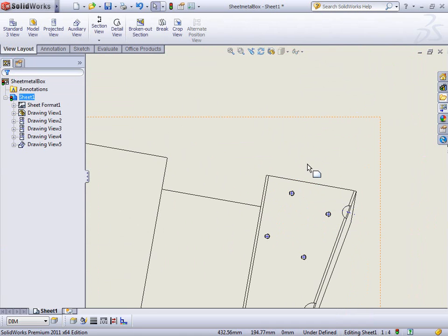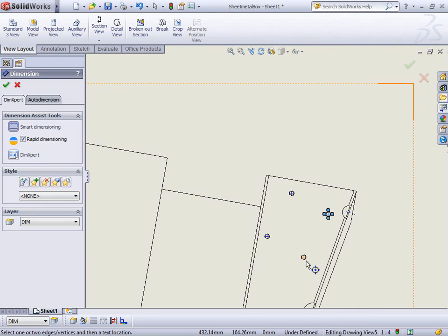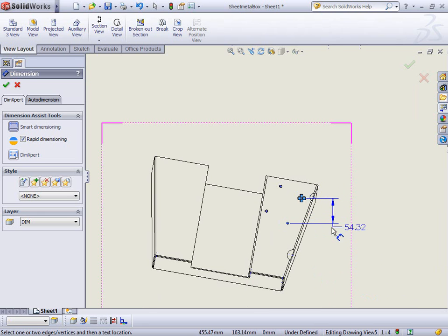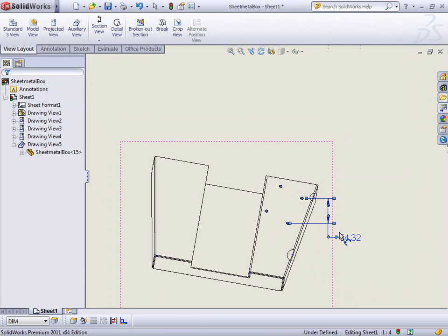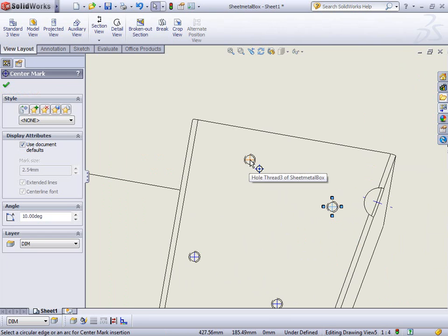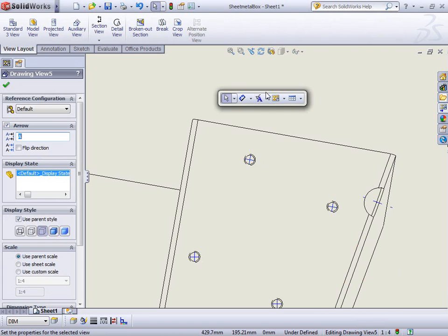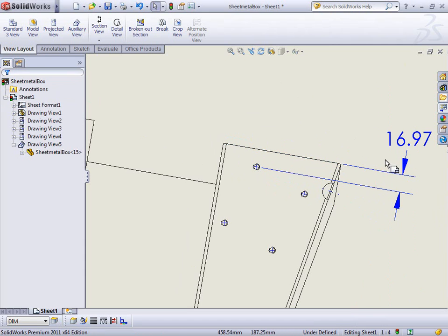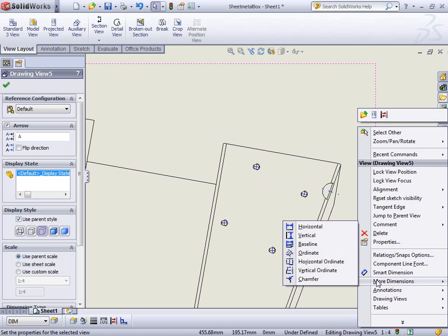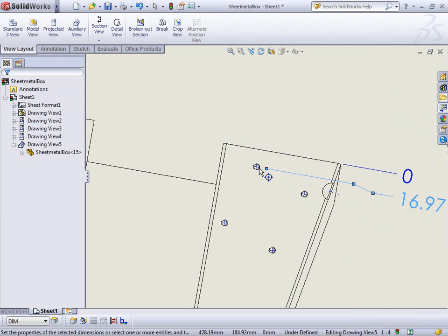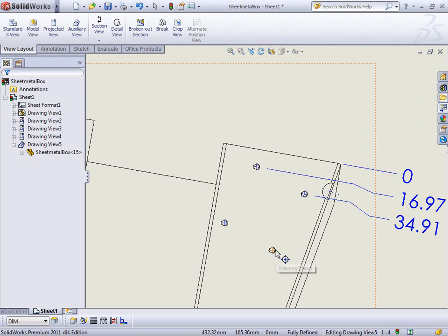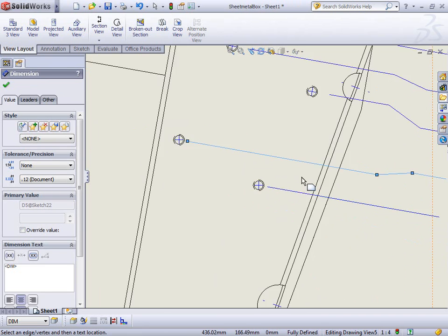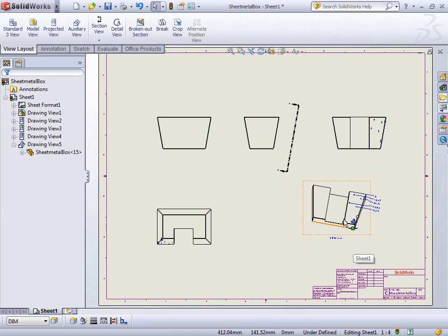And I'm also getting a good center point. So now I can do those types of things, or I can even rotate my center lines as well. We just call these out from that edge. Or even better yet, use an ordinate dimension. I suppose that would make the most sense. If I come back in, do an ordinate dimension, define this as 0. So now I've got those ordinate dimensions, have those other dimensions. Go ahead and put in some other reference.